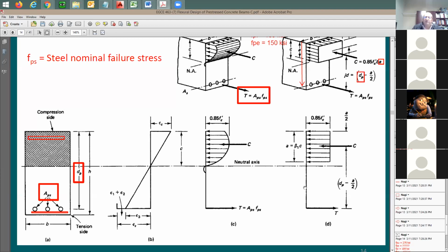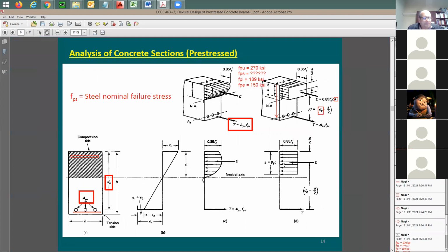Like what you have in your homework 5, right? If you recall, the beam failed because of excessive tension. It couldn't take it once you put it upside down. So once you add some conventional rebars, like number 4 or number 5, a few bars top and bottom, it's going to help in the strength, and also help to control the cracking in your beam, and also for fabrication and hauling the beam from one place to another.